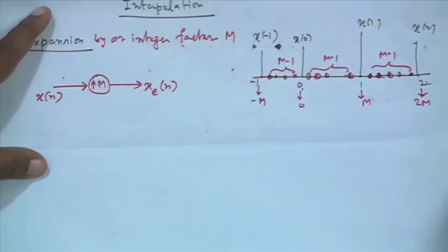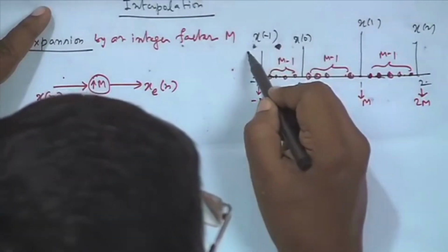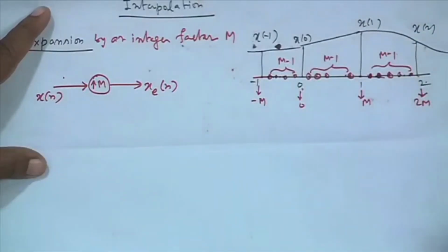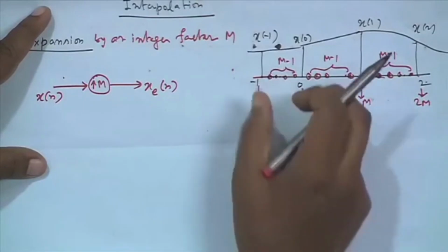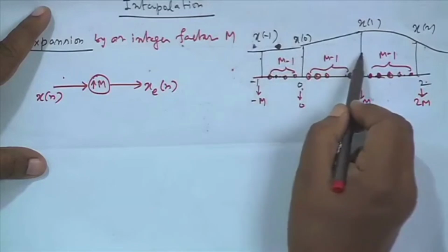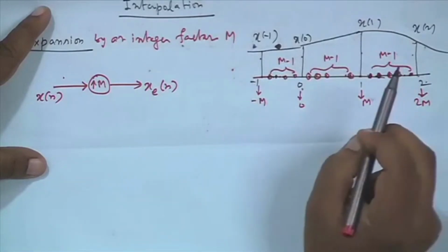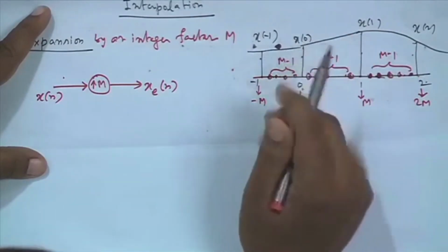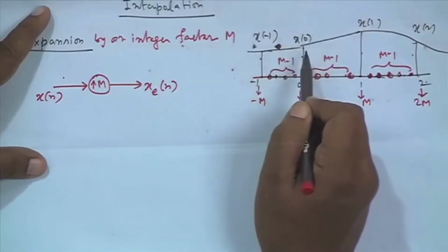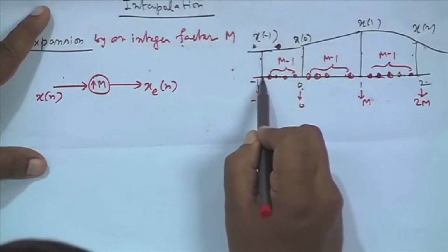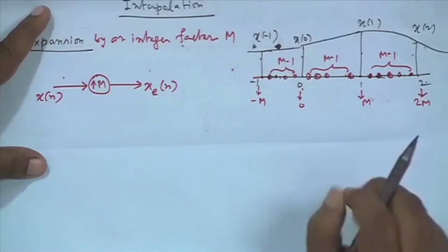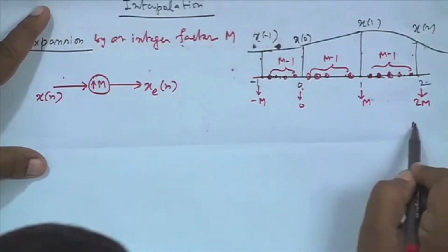It is like this. Suppose this was obtained by sampling an analog signal of this kind. You use so much sampling period, this much sampling period. So, your 0th sample, first sample, second sample, third sample, like that. Now, what is happening? After I sampled, the analog waveform has disappeared. So, I do not have the waveform again, but what I am doing is creating new sampling points, as though my sampling period has gone down and sampling frequency has gone up by a factor m.